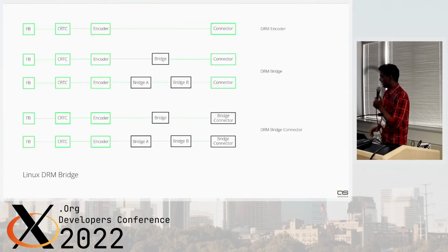This is how the simple MIPI switch looks, but we can see how this can be implemented in Linux. This is what a typical DRM bridge looks like. All the bridges are in a tree fashion. So if you want bridge A to N, you can connect bridge A, bridge B, bridge C. The idea of all these bridges is to attach and detach during runtime, so the pipeline can get access to them, and the bridges can go on up to where the pipeline decides.